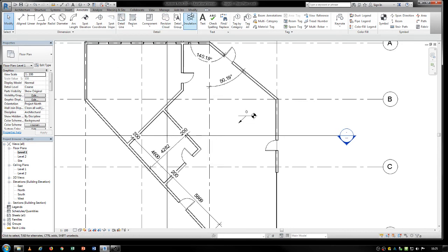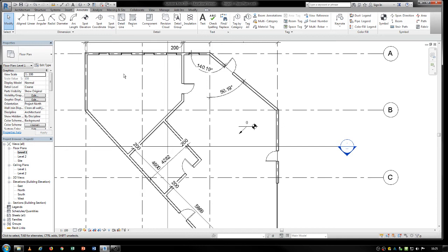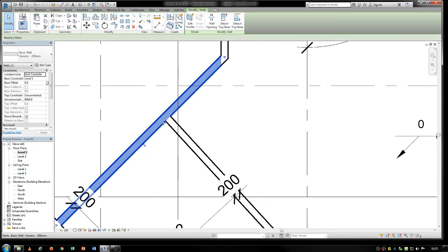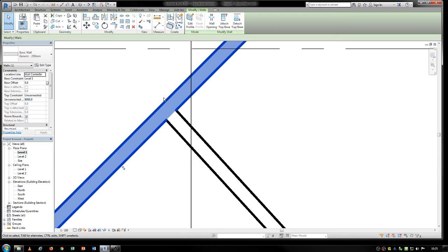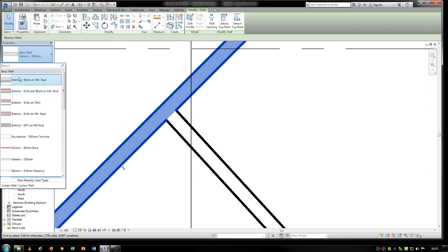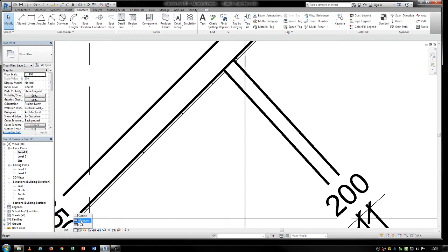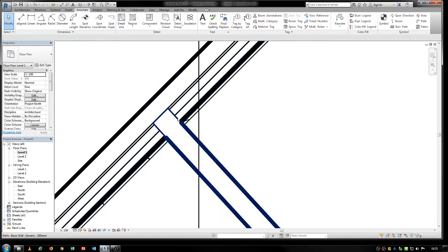Okay, so here, remember Branko was talking about you're showing 3 details in your project and all that kind of thing. So that's where you do a lot of the faking of that thing. When you're working in Revit, you have specific stuff defined. So this is a generic wall, meaning that it does not have any details in it. If I define a wall that actually has details in it, like one of these, and when I present this in a fine or medium mode, you can see some of the detailing of where the studs are, where's the core, what's exterior, what's interior are showing up.